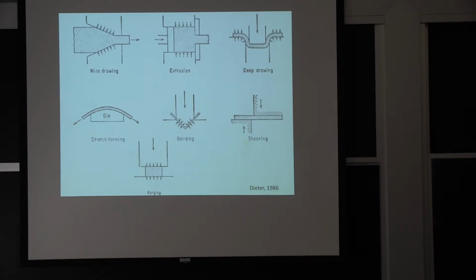If we are a stainless steel that's not magnetic, that's actually a way to verify. So if you want to know if you have the cheapest stainless steel or a higher quality stainless, you put a magnet to it. If it's not magnetic, it's not the typical steel, right? Most steels are magnetic, ferromagnetic. So when it's not magnetic, it means that it managed to remain, if you look at carbon steel, in the high temperature phase. And the reason is you added nickel and a few alloying elements, a little bit of chrome, that just extends the range of stability of this phase.